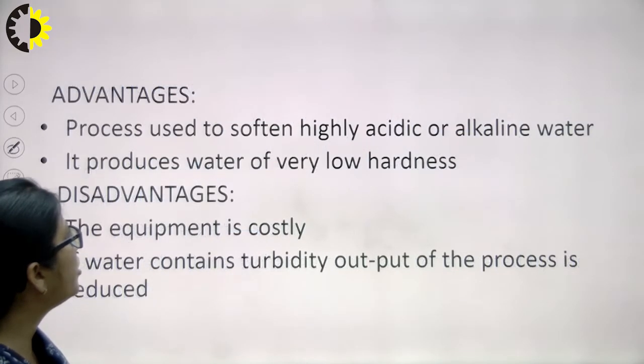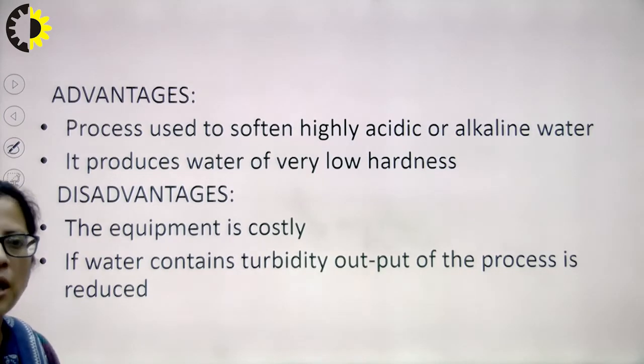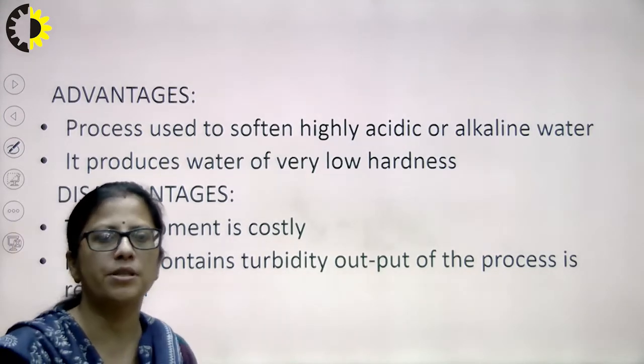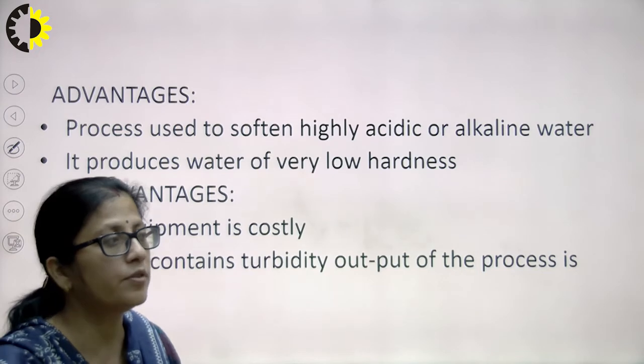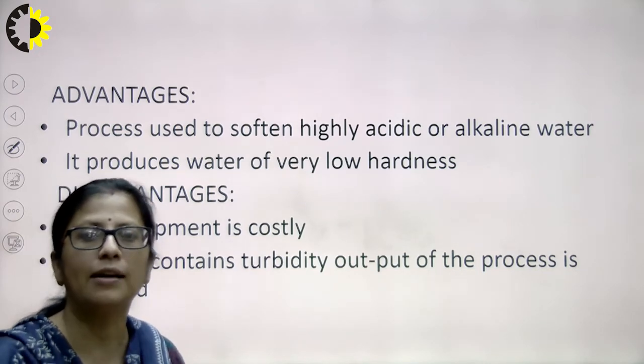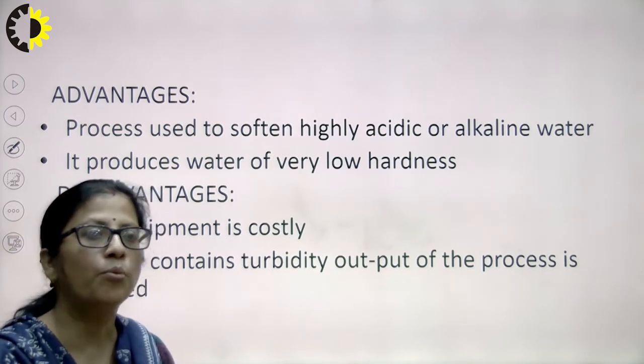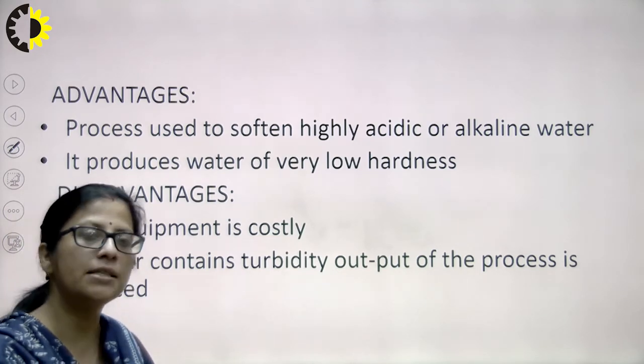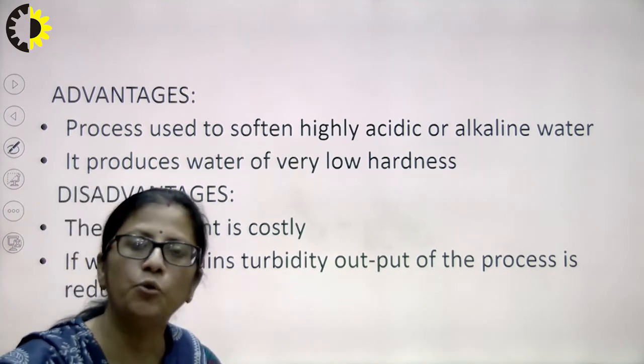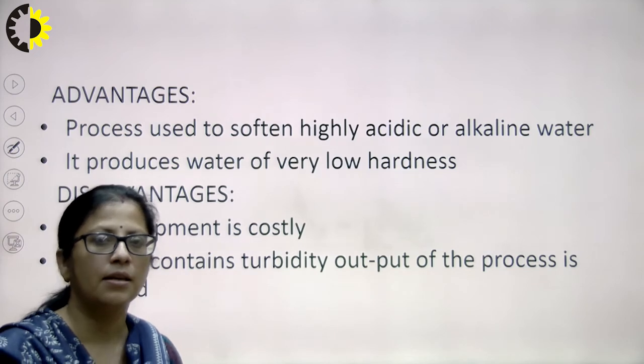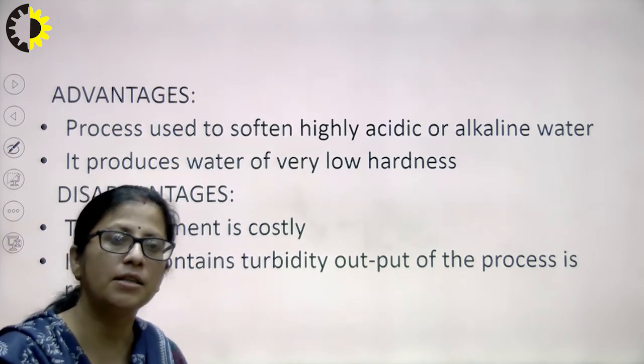So this is the regeneration. Coming to the advantages. Now this process is used to soften highly acidic or alkaline water, and water of very low hardness is produced. Less than 2 ppm hardness is left, that is the residual hardness.